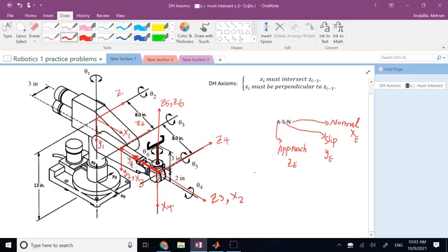And now we go to 5. x5 is perpendicular to z4 and z5. z4 and 5 already themselves are perpendicular at the rest point. So x5 has to be something like x2 and z3, and therefore I select it to be the same as them. Okay, so this is also going to be my x number 5, right? Perpendicular to z5 and z4. And if this is x5 like this and z5 is upward, then your y5 is going to be the same as z4.